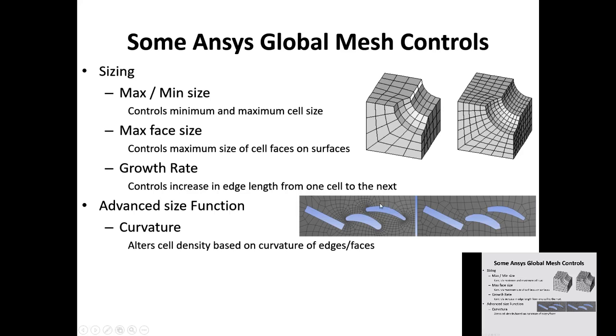Here, not as rapidly as in here. So therefore you need to resolve the curvatures well. You need to pick up the curvatures well. So for that you need a good grid resolution near these edges and curvatures, not just the boundary layers. So if you envisage any fast or abrupt behavior in your flow field, you need to pick up that behavior using a good grid resolution. Remember that.